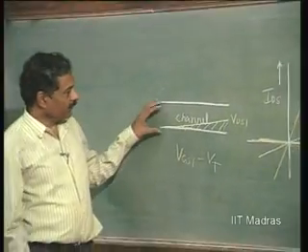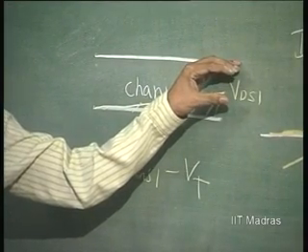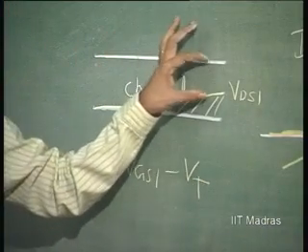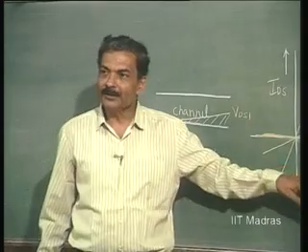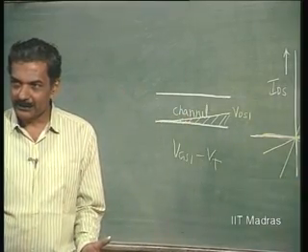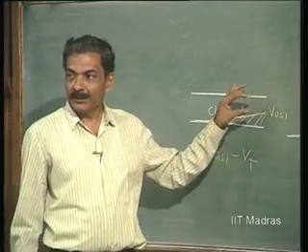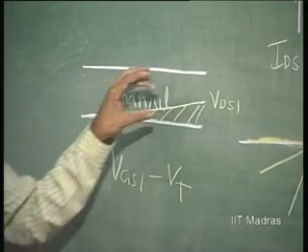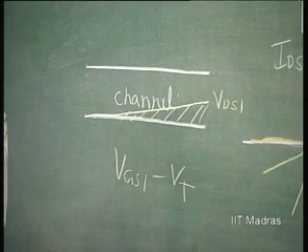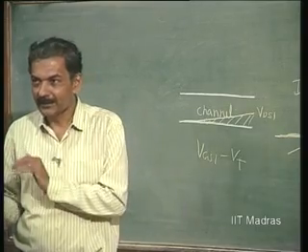So, this resistance, strictly speaking, is nonlinear because we are plotting ID versus VDS. The width or the depth of the resistance itself depends upon VDS. So, this is a nonlinear resistance. What happens to the resistance we can understand, because the width, that is the depth, uniformly decreases. So, effectively the incremental current for an incremental voltage should keep on decreasing.